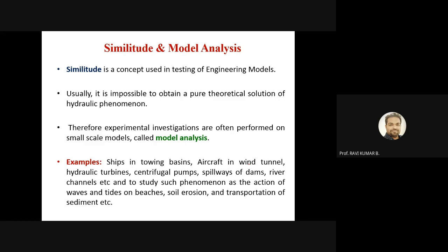A small replica of it, inside the internal hydraulic turbines. Similarly, when we are going to design the blades used in the hydraulic turbines, we have to do the flow analysis within the casing of the hydraulic turbines. So that is also flow analysis, right? So when you are doing it, we can take a small model and make the flow happen and see how flow is interacting in the blade passages, and how much amount of resistance is going to be created, that can be minimized by changing the geometry of the blades.